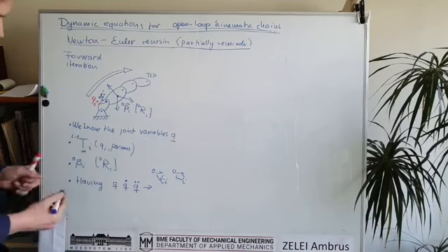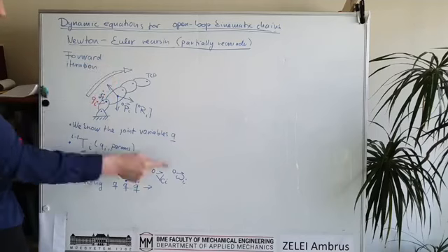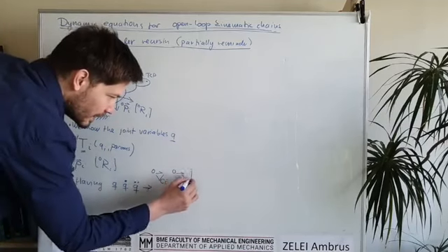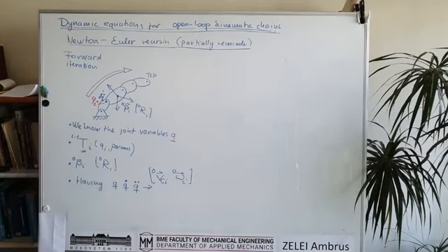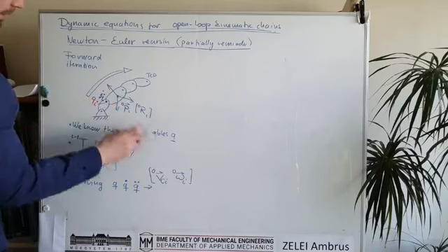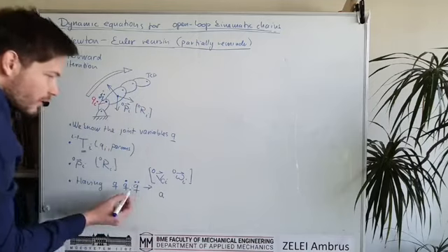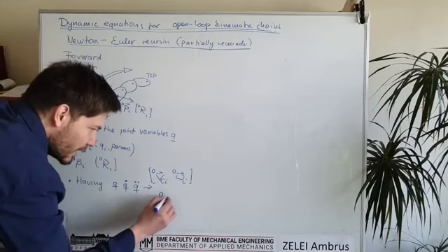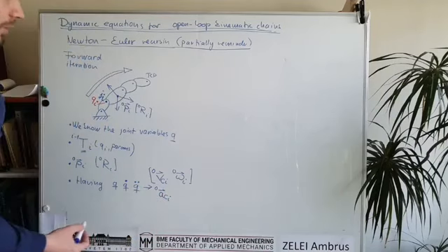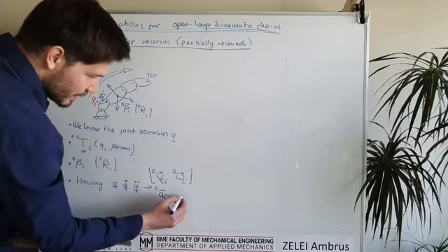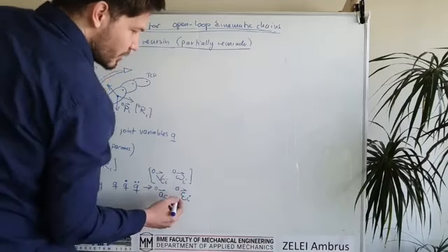We know that if we know the position and orientation, then we are able to calculate the velocity and angular velocity, and basically they are usually put in a bracket because together they describe the velocities of each link. And then after another time differentiation and using the joint accelerations, we can calculate the acceleration for each link center of mass, and also the angular acceleration for each link.